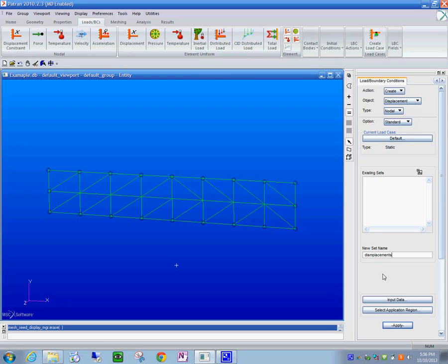That's the name of the set because you could create several conditions, like simply supported, or support fixed on one end, which is what we're going to do. And using the same geometry, you could potentially create several models. That's why we need to give names, and then later on, we build a case that has all those names.